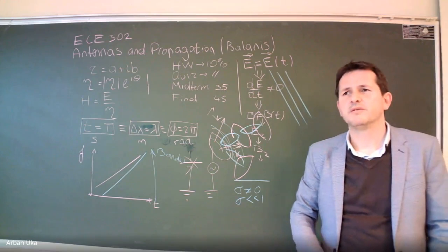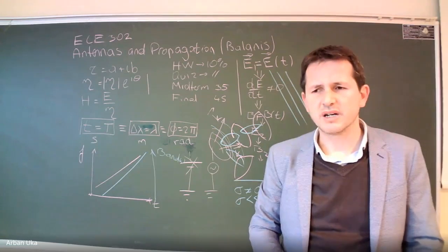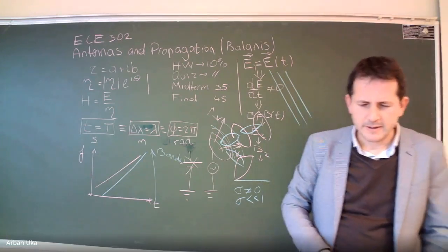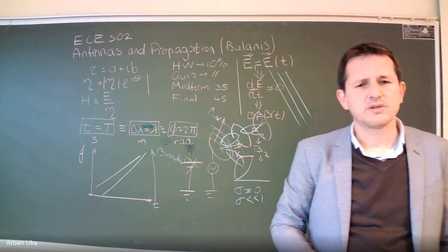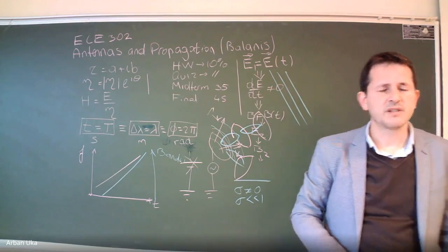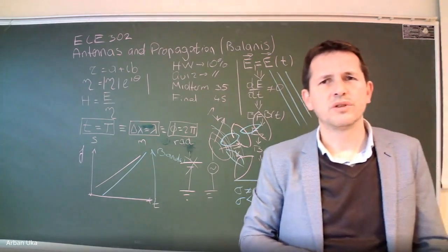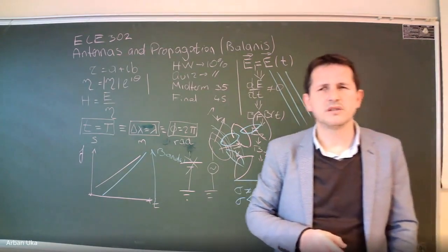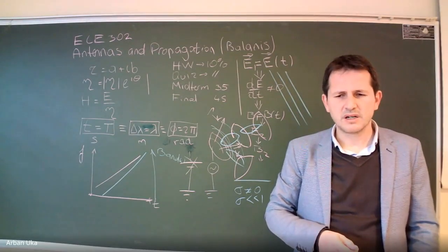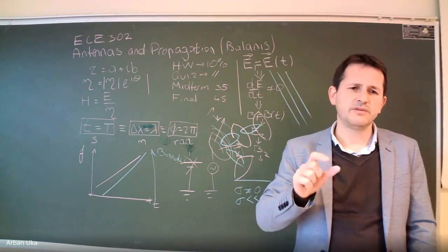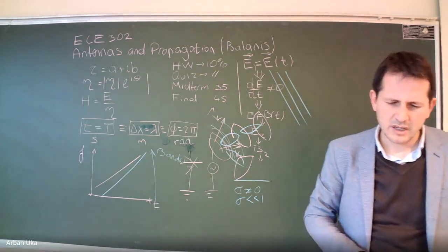Maybe, not maybe, but for sure, the next closest point where we could have had a discussion regarding the generation of the different shapes of waves was in the waveguides. So in the waveguides, we have seen, for example, some transverse electric wave, mode 1, mode 2, mode 3, or if you have both waves, you have TE11 or TE21, and these are different waves which behave differently whenever they are bounded in a region like a waveguide.